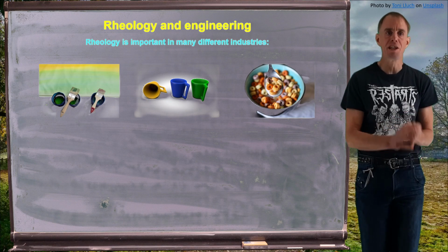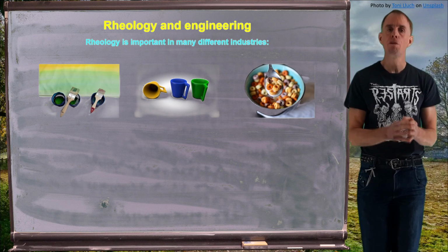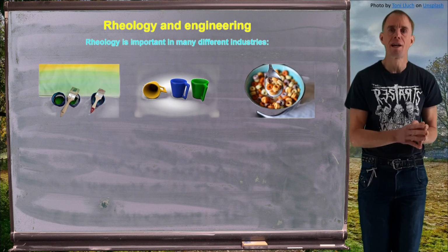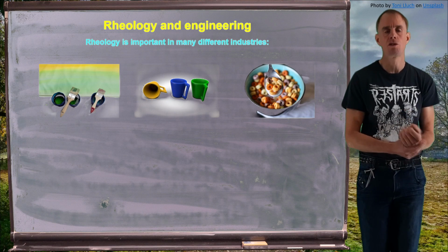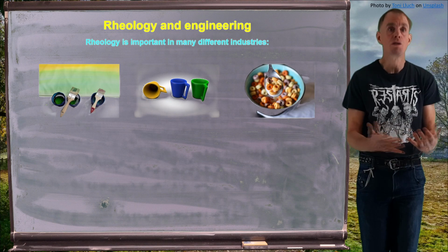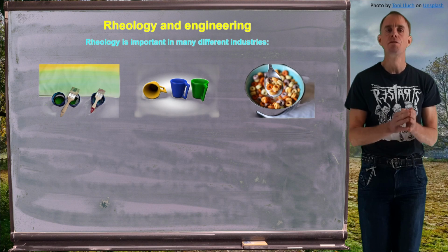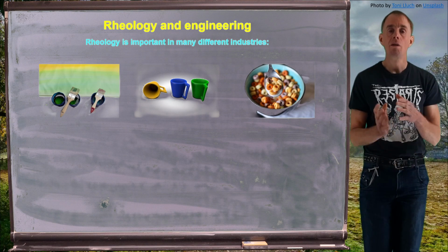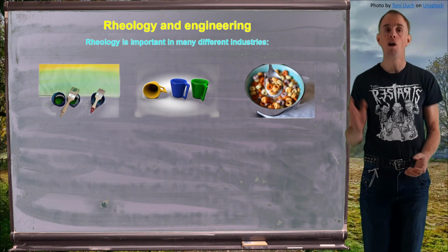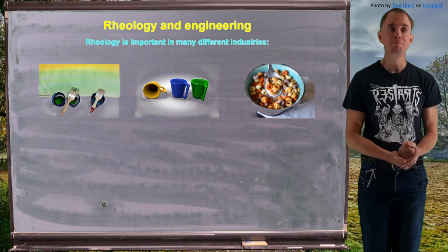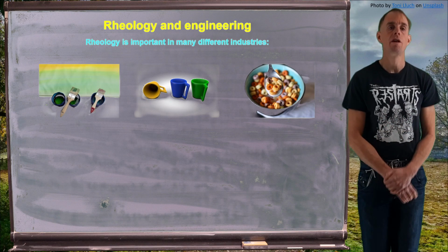So what we want is a predictable, reliable shape to be made by this process, and the properties of the material will largely designate whether that shape gets made or not, because some polymers will deform horribly after shape forming to produce something that bears no resemblance whatsoever to the shape through the die from whence it came. So understanding the rheological response of molten polymeric materials, be that petrochemical-based polymer or food-based polymer or biopolymer, is actually very, very important when we come to do shape-forming operations with these materials.